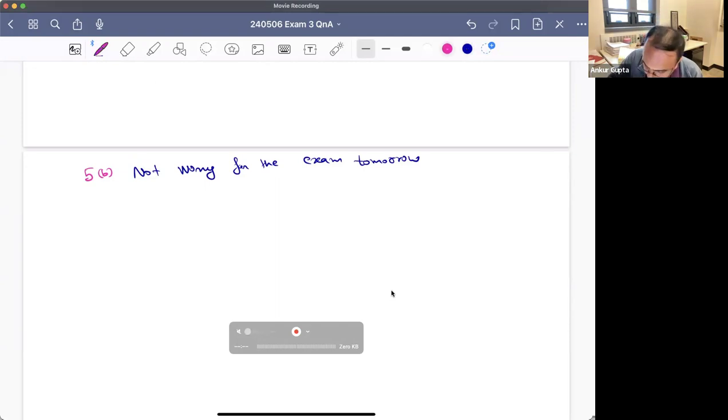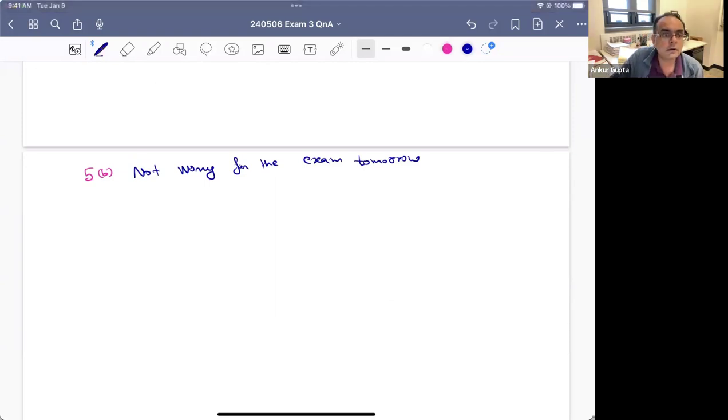So the main idea here is, and I forgot, let me just check the solution. The pi in the solution is T by rho omega square R to the 5. The main idea behind this particular problem was that T is proportional to force, which is proportional to stress, and that stress is proportional to 1 by h.